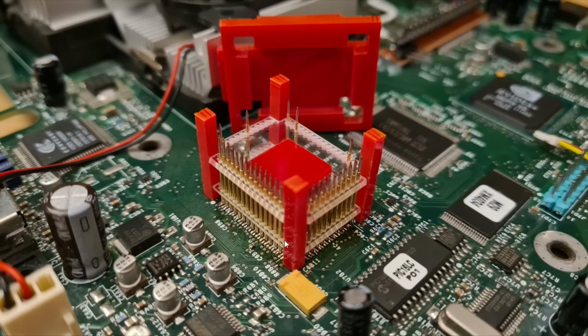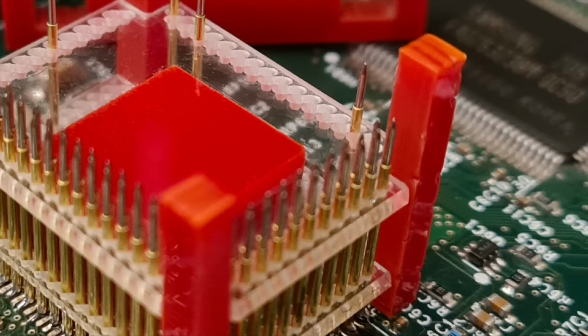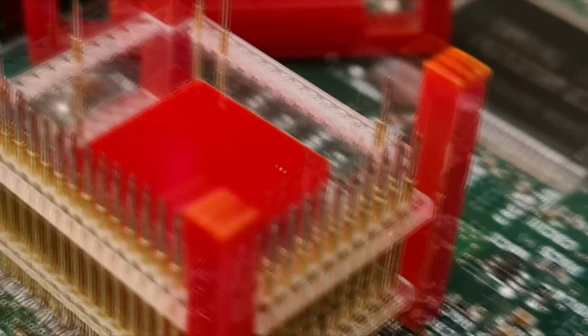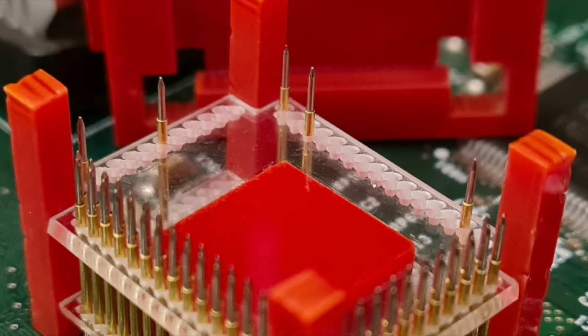My first attempt was this springed pin, kind of a Japanese temple looking thing. I think it's pretty cool, but it didn't work very well. These pins are 0.68 millimeters wide, and the pin pitch here is 0.65 millimeters, so I had to stagger them. If you look closely, they're in 2 rows here. And it took quite a long time to get this assembly properly sized for these pins, because I was using a laser cutter, and the precision required was quite fine.